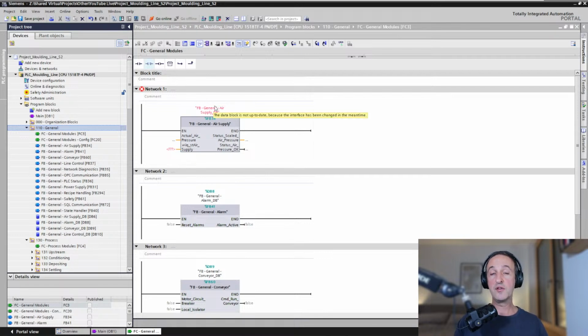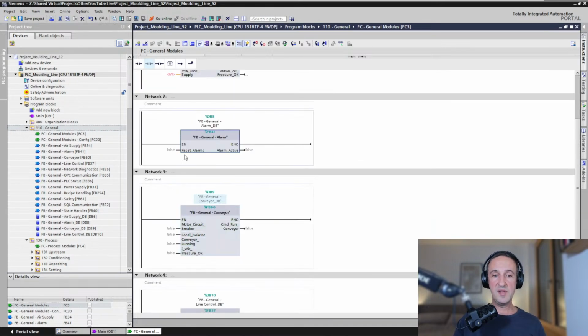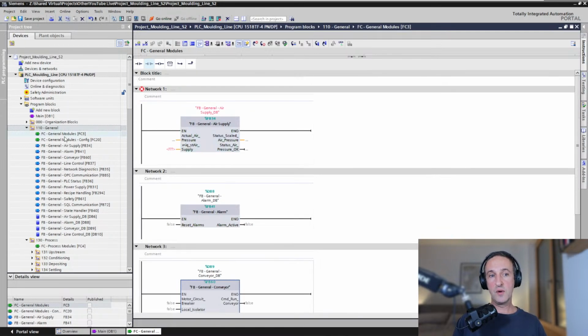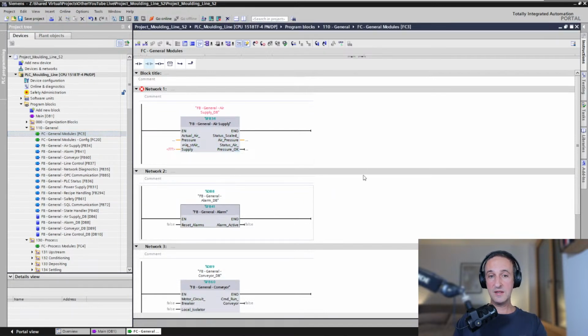I'm not going to do that now, but if you compile this, then only this instance DB will be initialized. And because these ones have all been created as single instance DBs, you will not affect the instance data of these blocks. So this is what I normally do if you're calling blocks into a function that is not being used in other places, just one place. I would suggest you call them with an instance DB because it is more safe when you do edits online, when you make changes during production.